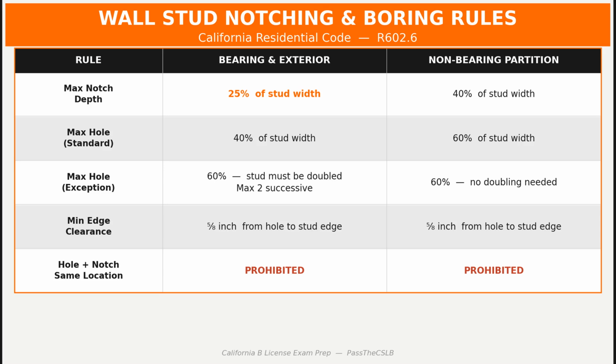Inspectors verify this on every framing inspection. The calculation is the same process as every other end notch. Identify the actual depth of the rafter, divide by 4. Engineered roof members, prefabricated trusses, I-rafters, glulam ridge beams, follow R802.7.2. No cuts, notches, or holes without explicit manufacturer authorization or structural engineer approval. Same rule, same boundary, same reason.